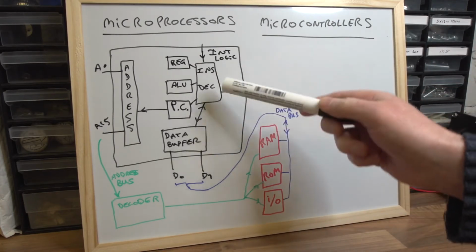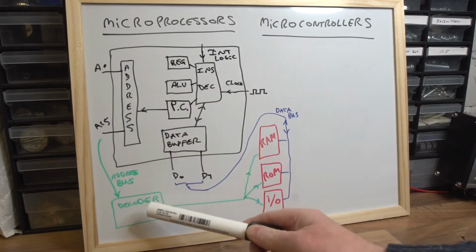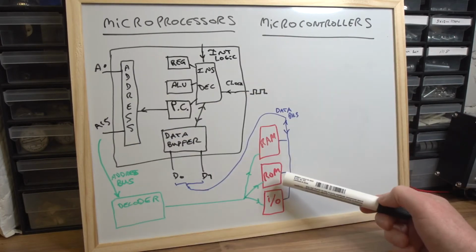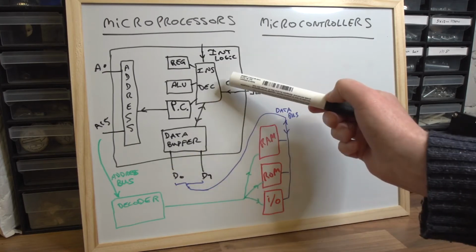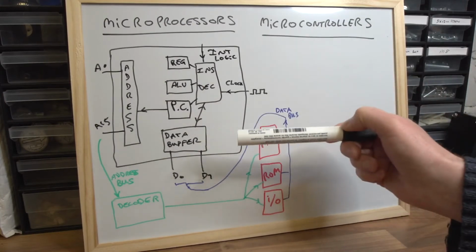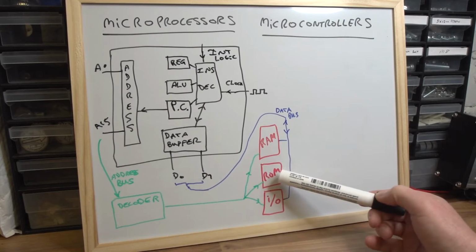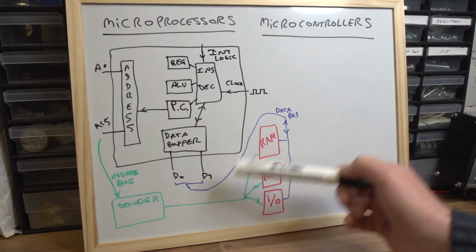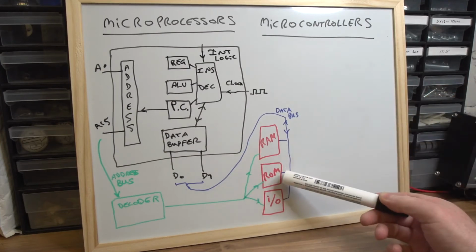Well, it's the same thing really here. It's clocking the instruction decoder. It's addressing through a decoder device and taking the instructions one at a time from the ROM and loading it into the instruction decoder. When that's finished, it goes click to the next instruction. The program counter is incremented and the address bus again goes to the ROM to the next instruction, and so on. So it's reading instructions one at a time, going through the memory of the ROM.